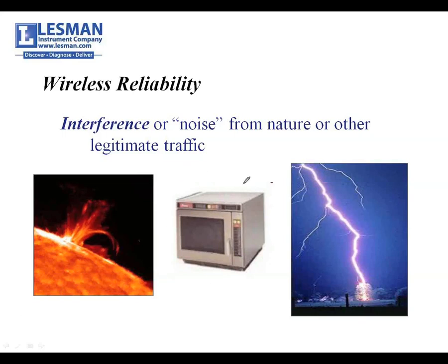This guy in the middle is a troublemaker, especially old microwaves because they tend to be pretty powerful and a little bit leaky. But through some miracle, if you take 2.4 gigahertz radio energy and focus it on water, it'll heat the molecules. So that's one of the reasons why that's an open government channel, is because of this guy right here. So when we go and do radio surveys, microwaves don't run constantly, so you don't know when they're in there. All I want you to be aware of is if there are microwaves in the building, you need to let us know, because we need to make sure that we can avoid them or shoot over them or around them.